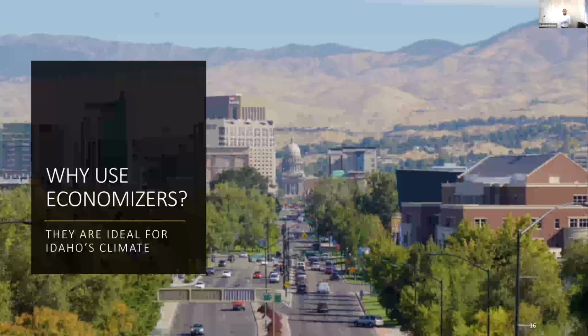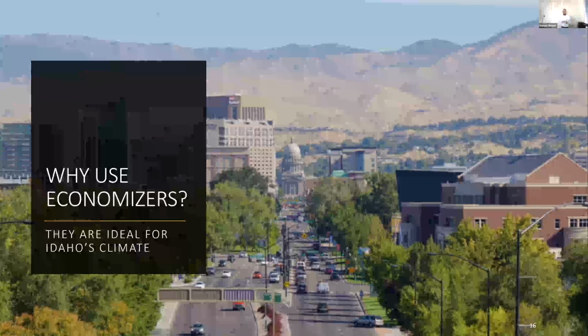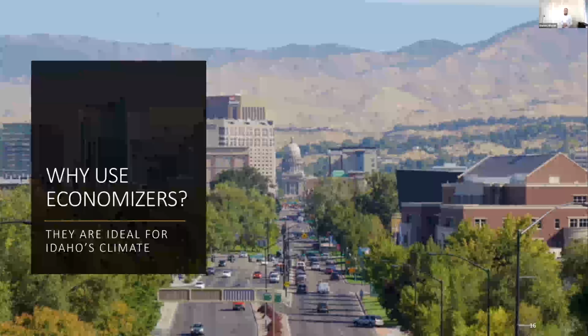So it's ideal when you have cool, dry air during the day between 8 a.m. and 4 p.m. when it's between 55 to 70 degrees Fahrenheit out there. And that happens in Idaho's climate quite a bit. We're climate zone 5B and 6B, which means we're cool and dry. So when you're designing buildings in Idaho, we've got more economizer requirements than we do, say, in like Florida or somewhere else. It's just too humid and too warm.